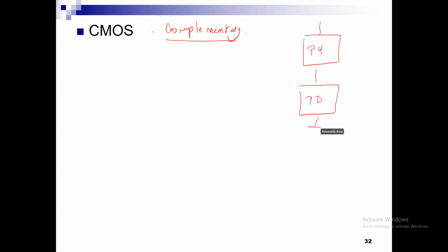In the context of the CMOS, one of the transistors will be on and will be pulling the capacitor to VDD or ground. And what is CMOS? CMOS is complementary MOSFET logic, okay? Complementary means I will have a pull-up network and a pull-down network.